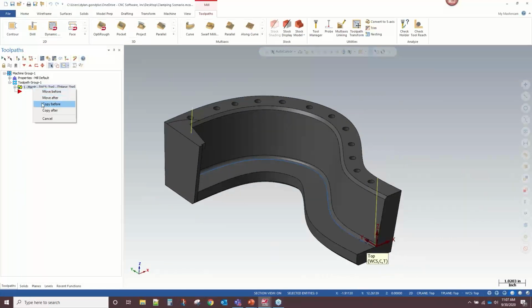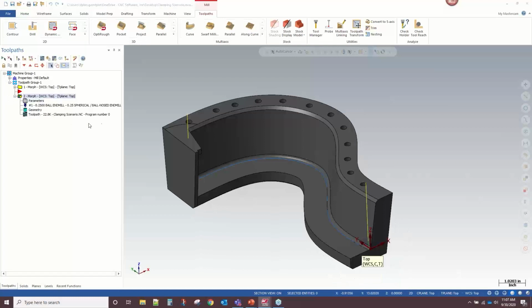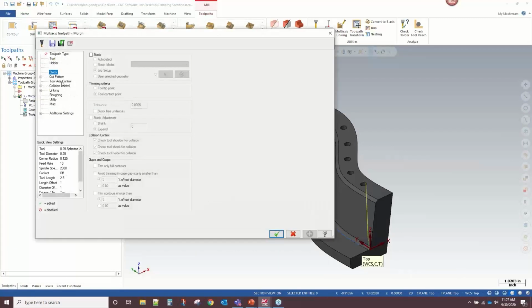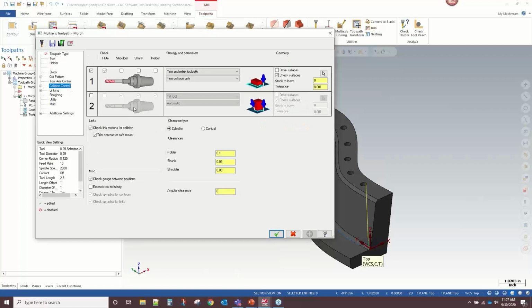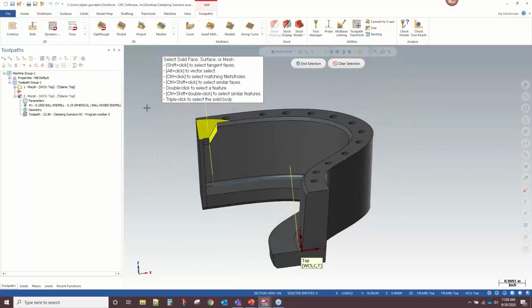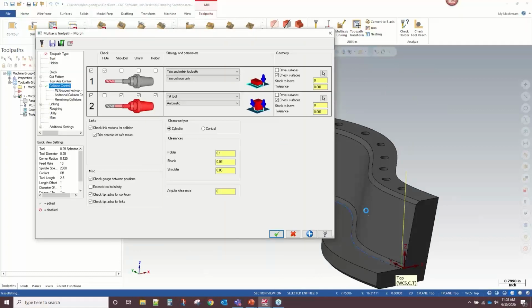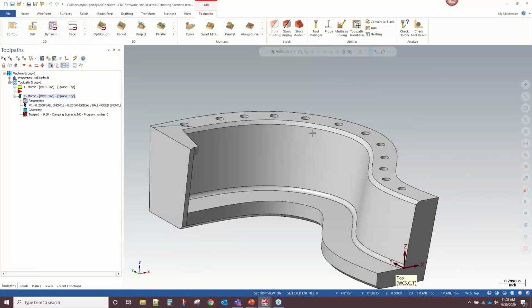If we jump into this morph, let me copy this down. In tool axis control, I'm fixed to the z-axis. If I want to modify that motion to avoid that ledge, maybe I'll turn on a collision control strategy to tilt the tool if it comes in contact with the end overhang there. Simple enough. Let's generate that and see what we get.